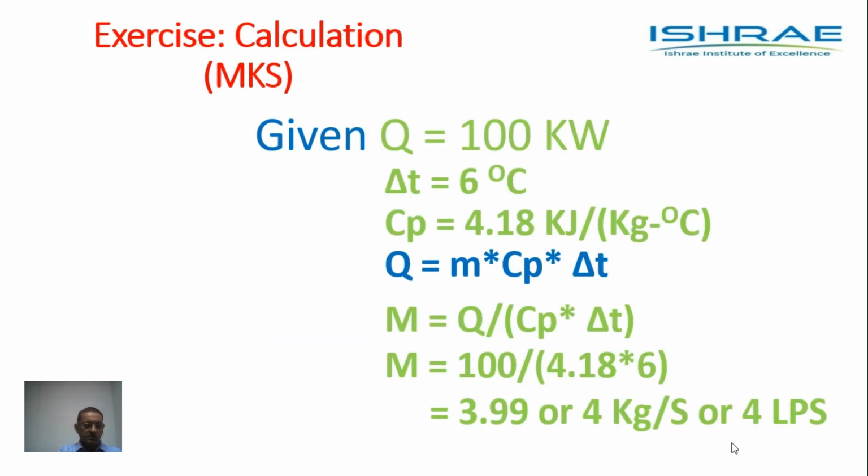Now, knowing this, the supply temperature is 6 degrees centigrade, the return temperature is 12 degrees centigrade, so we get a delta T of 6 degrees centigrade. Now, if we are given that we have a system with a cooling coil where the load is 100 kilowatts, can we compute the amount of water flow required per unit time? Well, why not? We can.